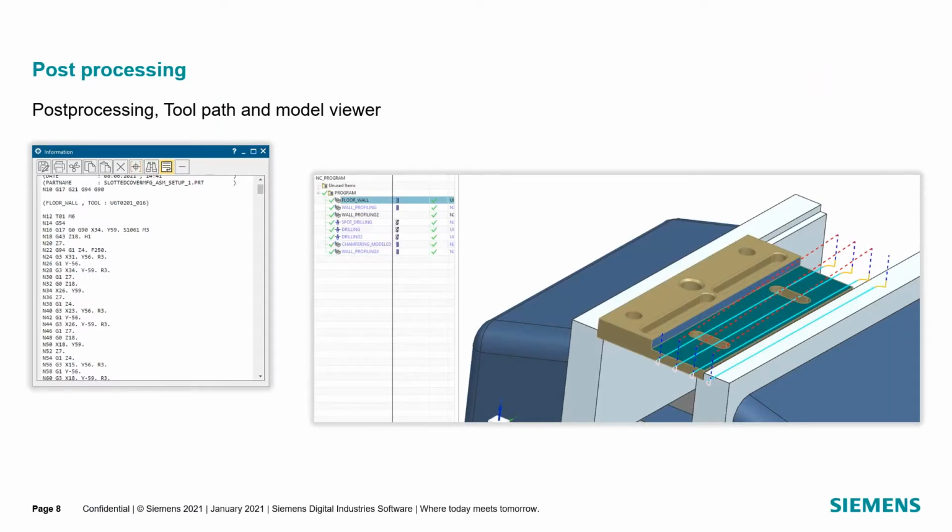Not only that, once we do this kind of thing, I think you need to validate your toolpath, whether the toolpath is proper. If I run this on my 2.5 axis machine, is it properly visible? Is there G-code, M-codes? I can view the toolpath with IPW, in-process workpiece, which can also be created on the fly. Now, the biggest advantage here is it depends on the controller your machine has. It supports all the major controllers, FANUC, Heidenhain, Siemens, or any other older controller. As long as it takes G-code and M-codes, we can support those outputs and give a specific output using the post-processing technique and then run your machine.